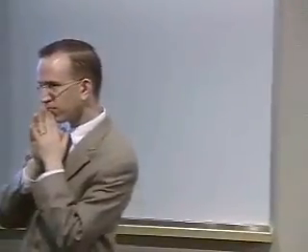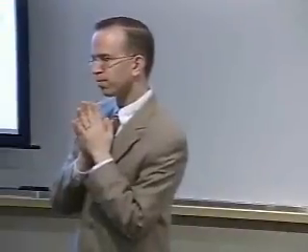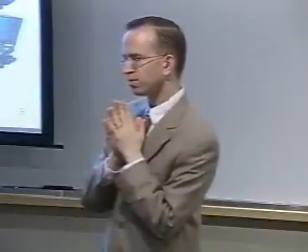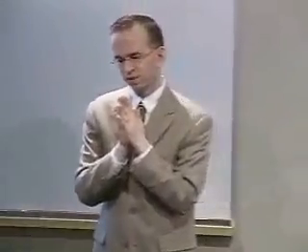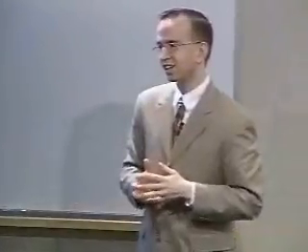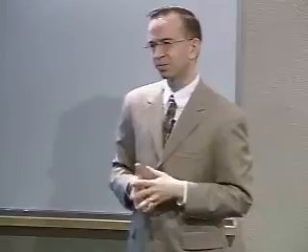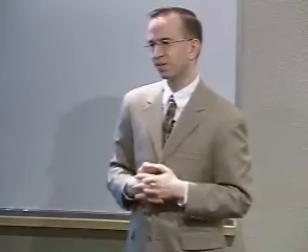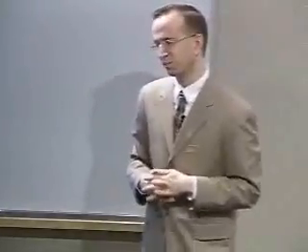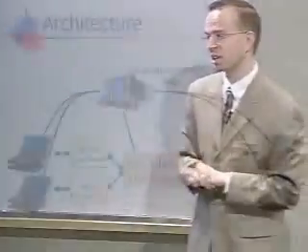For what kinds of wireless devices is coaxial cable a problem? A problem? Yeah, like is there some frequency range in which it is no longer a good medium for getting things to the signal propagation environment? I'm not aware of it. Certainly the higher you get in gigahertz, the more attenuation you get in the coaxial cable, but I'm not aware of any of that where it completely flakes out. Certainly if you can fab a device that's going to work at all, it can probably have some coax cable that it can work with. These coax cables are very short, I should say.